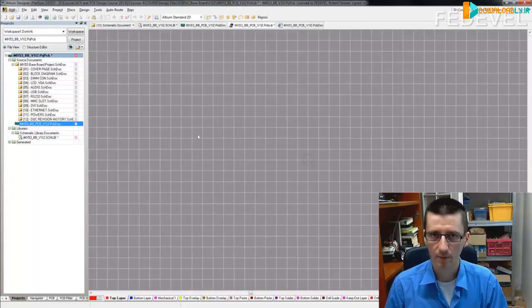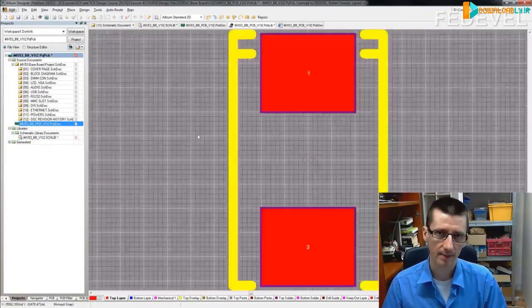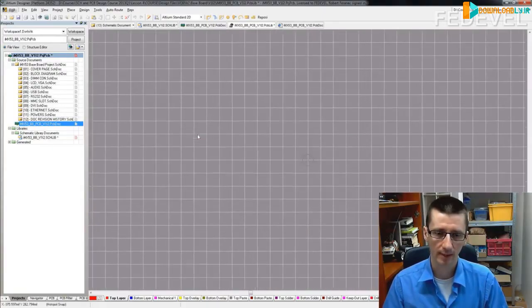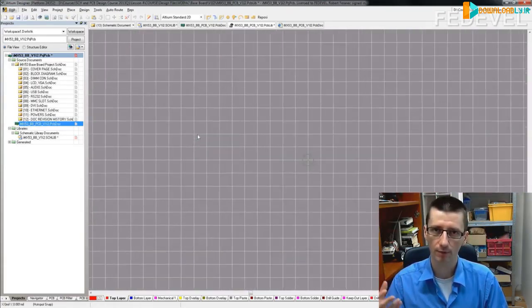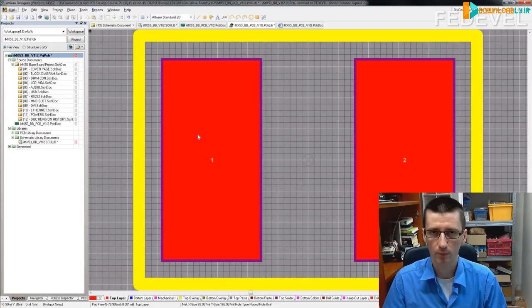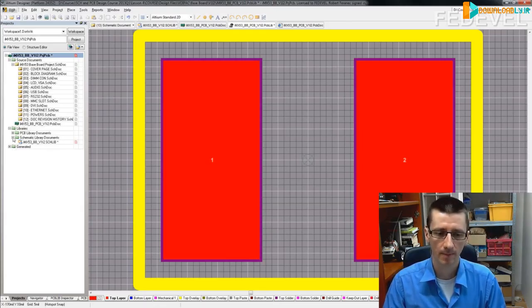This is a very powerful tool because if you have a reference design, you can create your PCB library from the reference design, so you don't have to create all the footprints by yourself, especially for difficult footprints like processor footprints. You just import it to Altium and create the library.